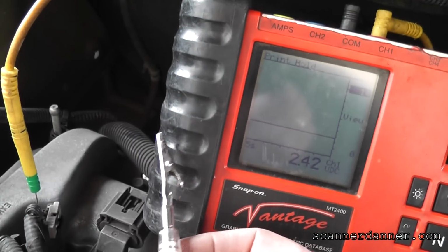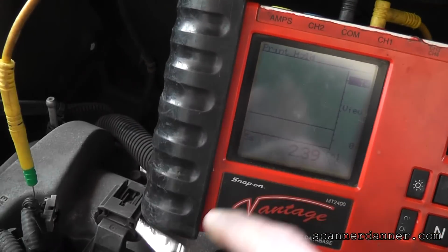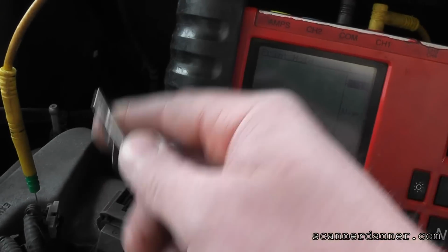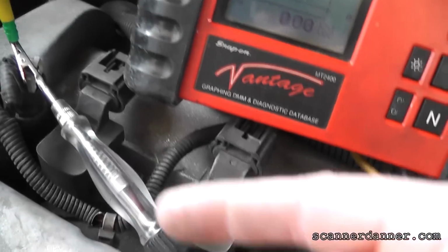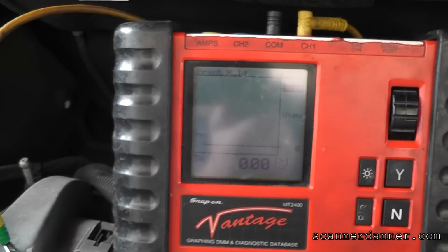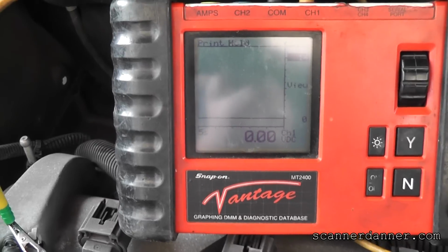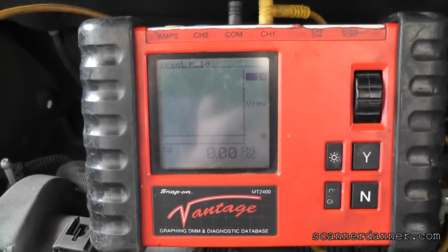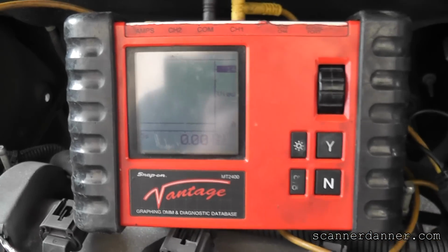What I'm trying to do now is just to prove that this is really computer circuitry that's checking this thing. And I'm going to do it with a test light connected to ground. What this test light's going to do is just simulate that there is some connectivity to ground through a solenoid. Now, it's not really a solenoid, it's my test light. And the current flow is going to be off here, but this should keep this code from coming back immediately. Let me clear the codes again. Let's display them, see if that code came back. It did, immediately came back.